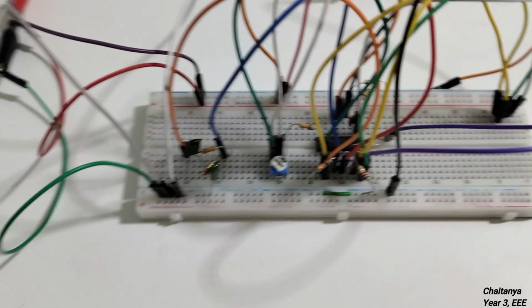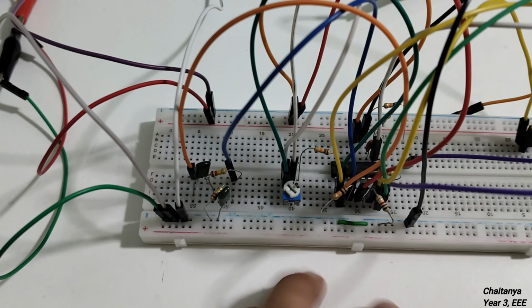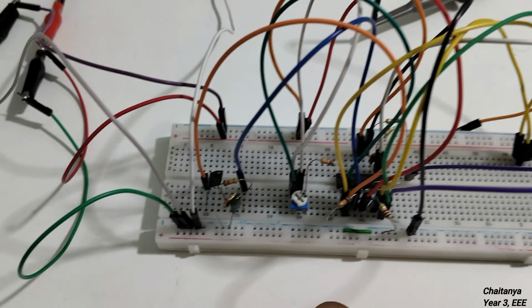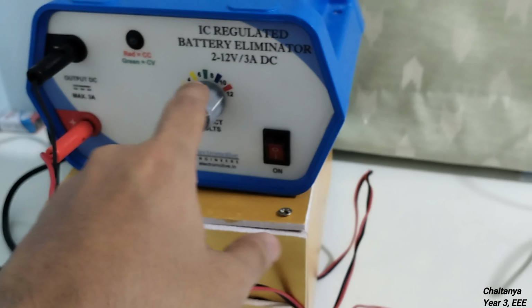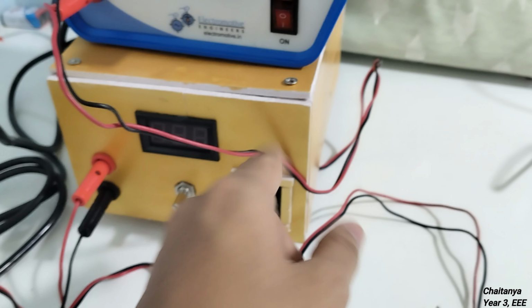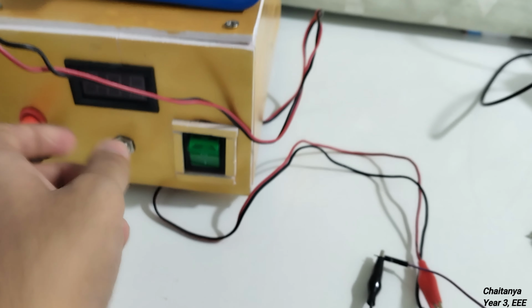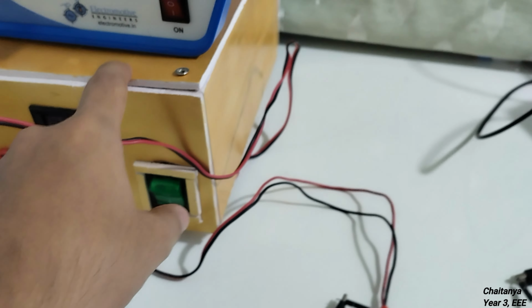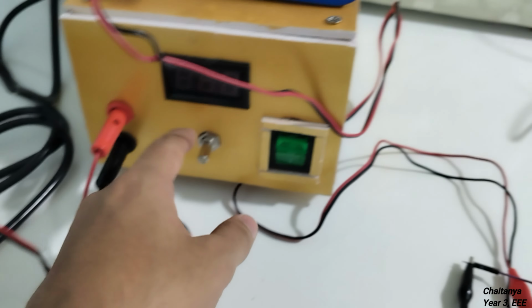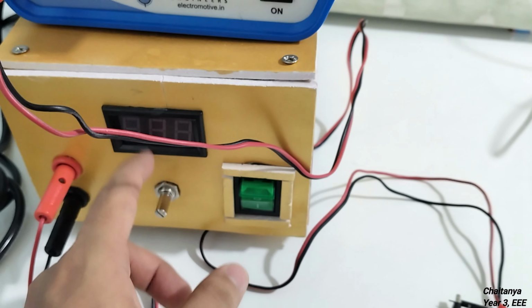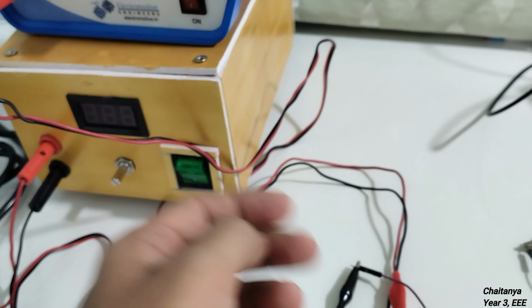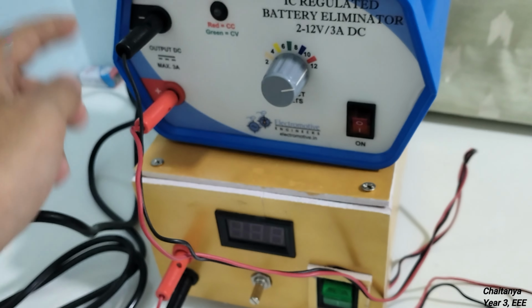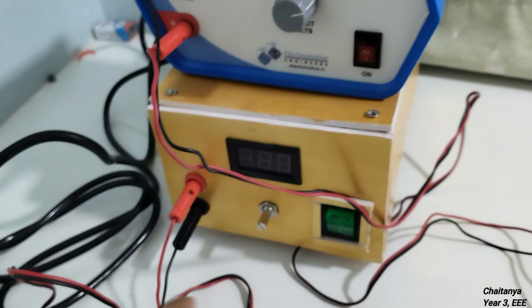Another thing is to show you the setup I have here. As we know, op amps need, this being bipolar, a plus VCC and minus VCC. So I have two supplies here. This is a ready-made supply which I bought, 12 volts, and this is an adjustable supply using a pot, which I made myself. It's a regulated power supply, and I'm going to set it to around the same 12 volts. When we have two supplies, if you common the ground between them, you have this positive terminal here and this negative terminal, and this has positive and negative.